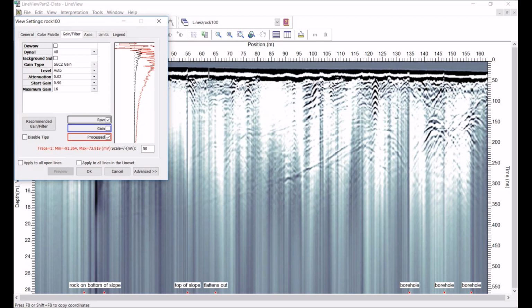So that's what wow looks like on the GPR line. Quite different, isn't it? Let's look at it on the GPR trace level. This box here shows the GPR traces, which changes as I move my mouse cursor across the GPR line. Notice how the GPR signal near the top does not oscillate around 0. I'm looking up in this section in here. It's not oscillating around 0. It's offset to the right of 0. This is the low frequency wow that I was talking about.